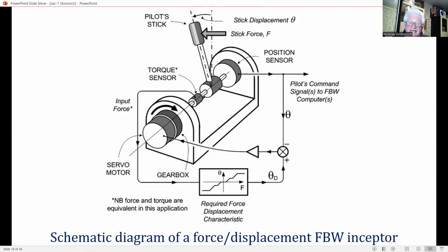This force is sensed by the force sensor, and the stick force or displacement controller generates zero stick displacement demand at this point, as it is below the breakout level. The servo motor force balances the force the pilot is applying, and the stick is displaced by a very small amount from the central position to provide the necessary motor current from the servo amplifier.